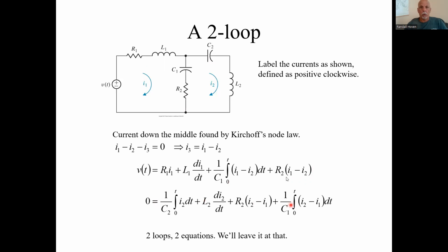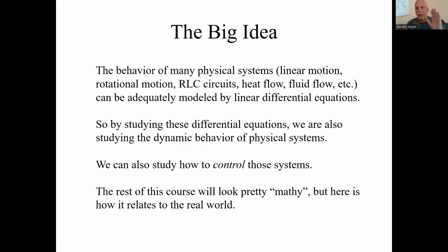And this will be the equation for this loop. I'll have, what is it? Okay, this capacitor, this inductor, this R, and this C. I have 4 different voltage drops around this loop. We got to be careful with signs again. So two differential equations for the 2 non-redundant loops. This can get confusing, I know, and I'm covering it very quickly.